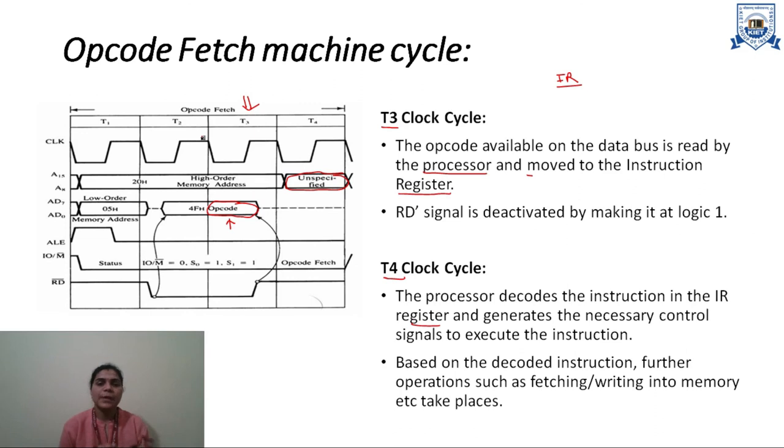It can be a memory read, a memory write, an interrupt request, or an interrupt request acknowledgement. So here we have a collection of T states or clock periods, and in these lines the processor is placing the address on the address buses. ALE will be active to denote that the multiplexed buses are carrying address.